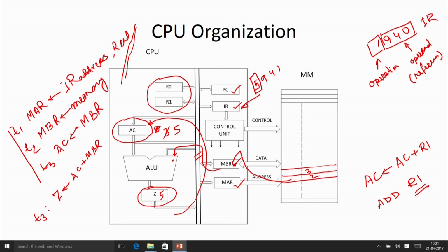So, it is transferred to the internal data bus of the processor, and from the bus it comes to this. This result we are storing in the temporary register, because I cannot directly give it to the bus to transfer it to the accumulator, since there will be a data conflict. Already I have input data, and along with that I cannot give the output data to the bus. So, there will be a conflict of data.